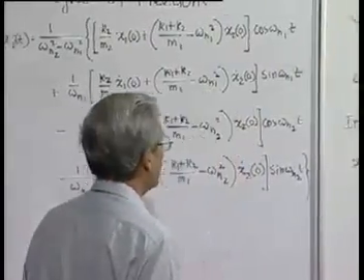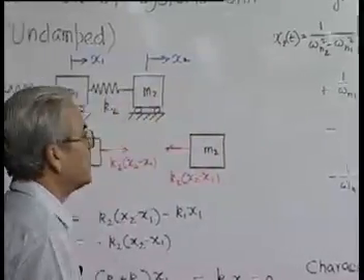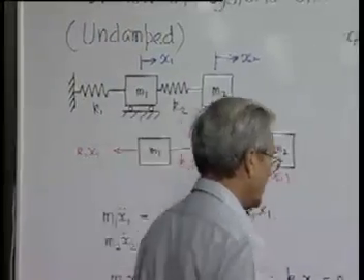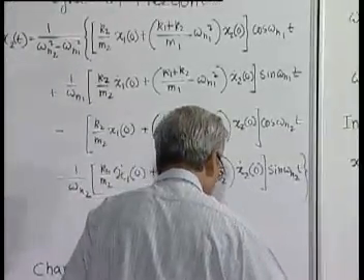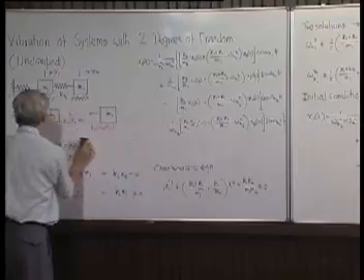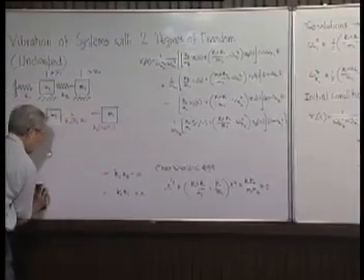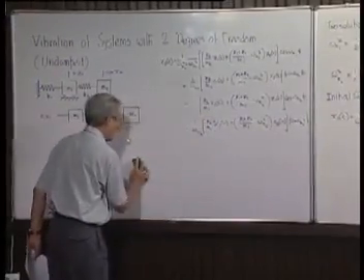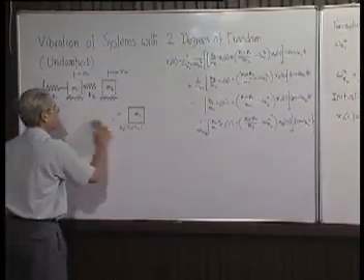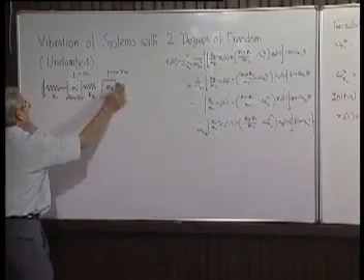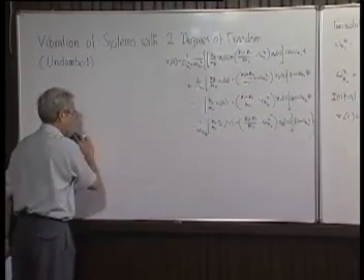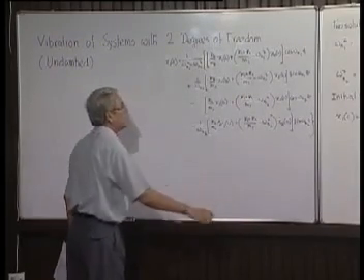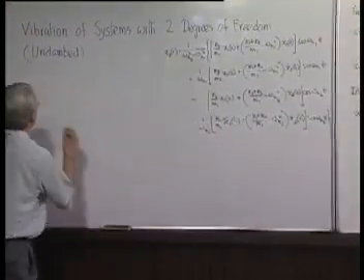So, these are the general solutions even for a simple case like a 2D freedom system, undamped free vibration. Now, it is very clear that they are all mixed up. That means two frequencies are involved, omega n1, omega n2, and obviously x1 or x2, none of them are simple harmonic. However, we can see that it is possible to give initial conditions, that is x1 0, x2 0, x1 dot 0, x2 dot 0 in such a manner